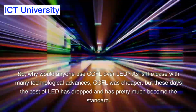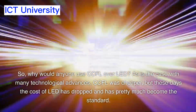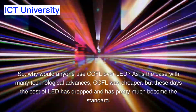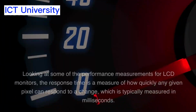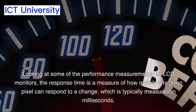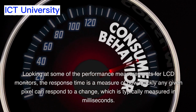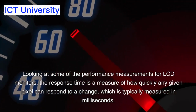So, why would anyone use CCFL over LED? As is the case with many technological advances, CCFL was cheaper, but these days the cost of LED has dropped and has pretty much become the standard. Looking at some of the performance measurements for LCD monitors, the response time is a measure of how quickly any given pixel can respond to a change, which is typically measured in milliseconds.